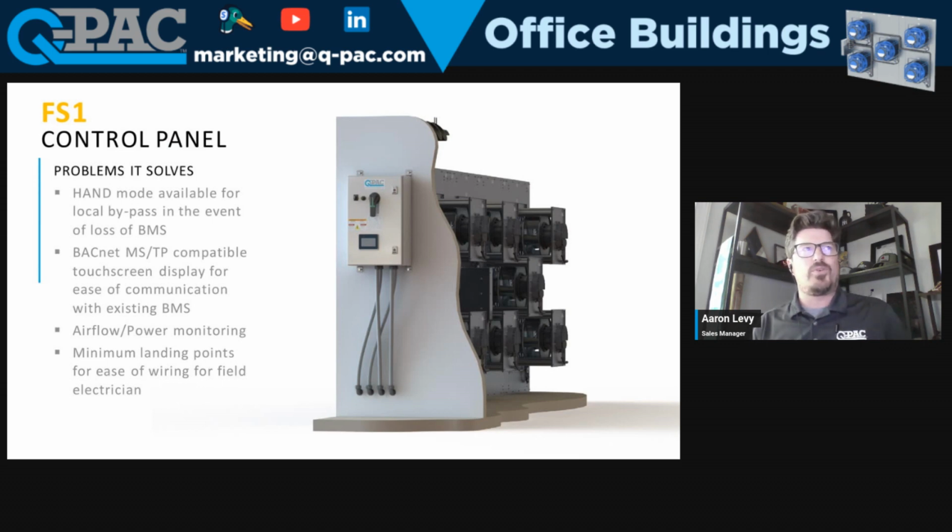And then of course we have our control panel outside. This is the main touch point for most contractors and everything here. For a premium controller, you'll have that 7-inch Schneider touchscreen display, which will give you CFM readouts, power readouts, static pressure, and individual fan status alarms. It does have a hand auto and off switch, which is on both the premium and the basic controller.